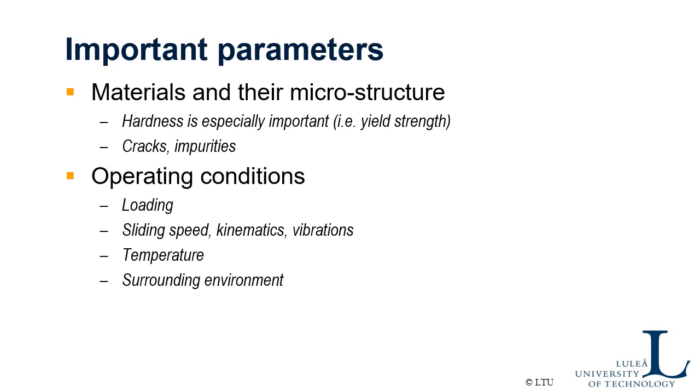The operating conditions are of course also very important. I mean, how high the load is, the speeds, how high the sliding speed is, if you have vibrations there, and so on. Temperature is important, definitely, and again the fourth element, the surrounding environment. If you are in a corrosive environment, for example, you may increase the wear rate. Coming back to that later.